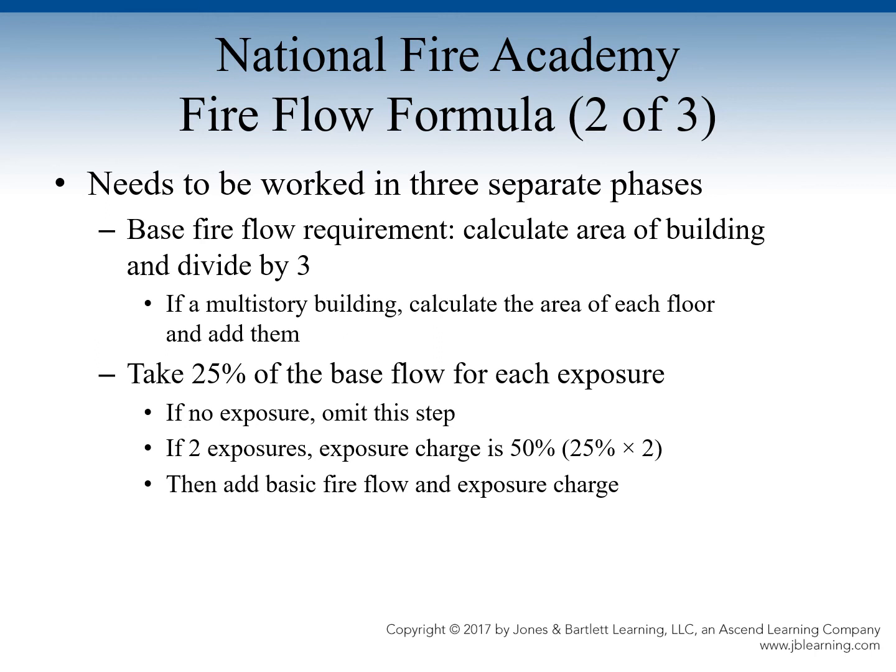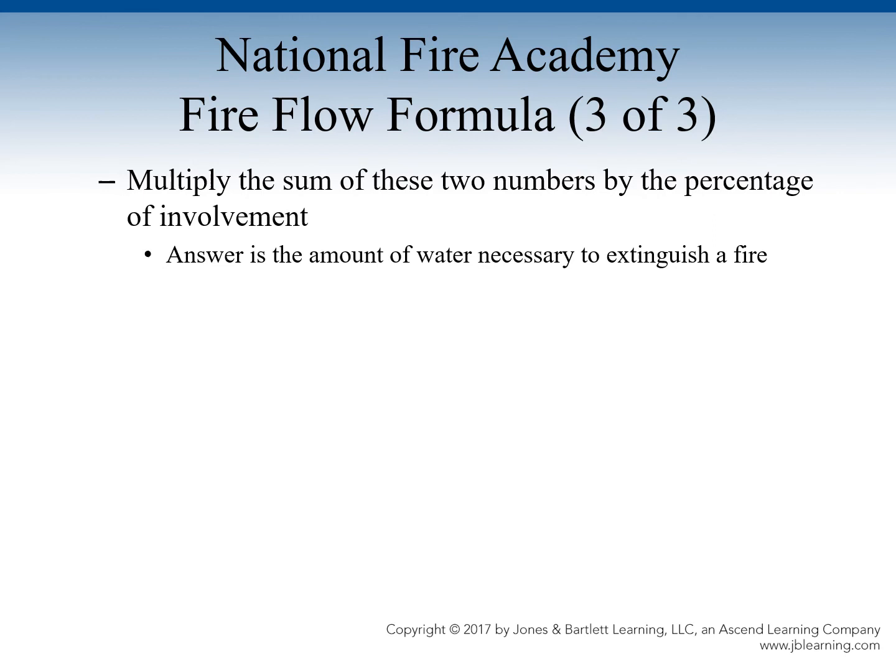Then we add the basic fire flow and the exposure charge together. Multiply the sum of these two numbers by the percentage of involvement. The answer is the amount of water necessary to then extinguish the fire.